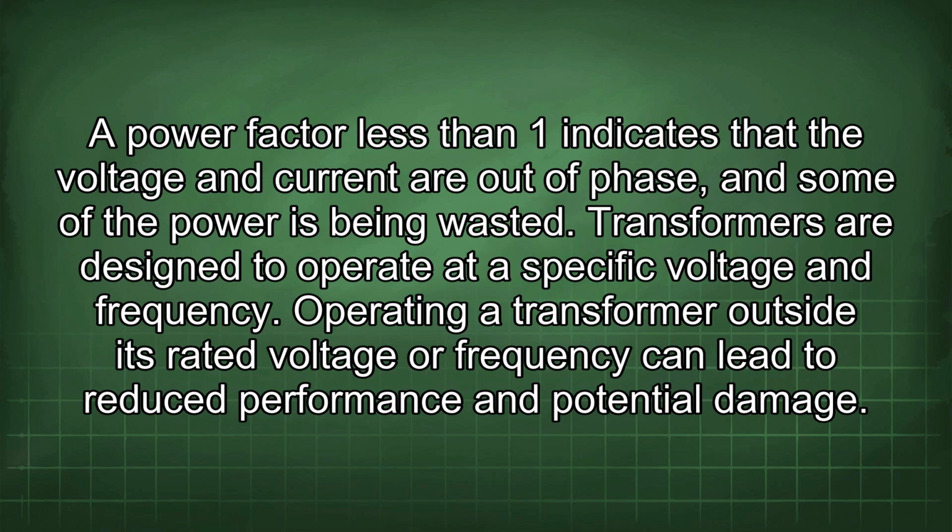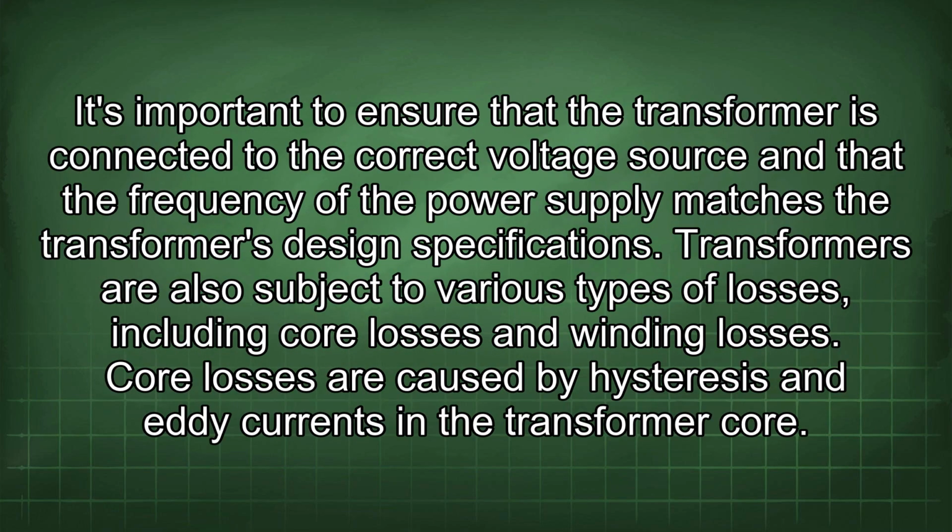Transformers are designed to operate at a specific voltage and frequency. Operating a transformer outside its rated voltage or frequency can lead to reduced performance and potential damage. It's important to ensure that the transformer is connected to the correct voltage source and that the frequency of the power supply matches the transformer's design specifications.